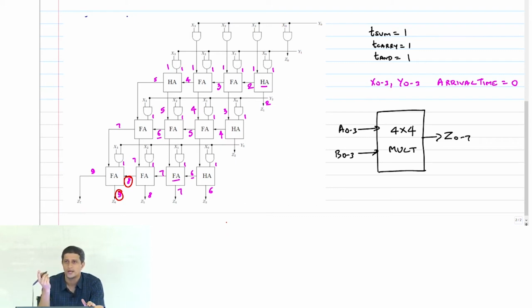Both, right? Effectively, what this is saying is there are multiple critical paths, all with the same delay. So it is impossible to sort of optimize this because everything is equally critical. Now if you want to optimize one critical path, there should be another path which you can sacrifice delay on. Then you can optimize. But now there are multiple paths, right?